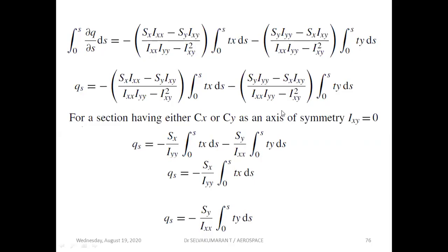Otherwise, you will unnecessarily assume some Sx value or Sy value, and unnecessarily calculate. You will try to calculate the Ixy value for a symmetrical section also.